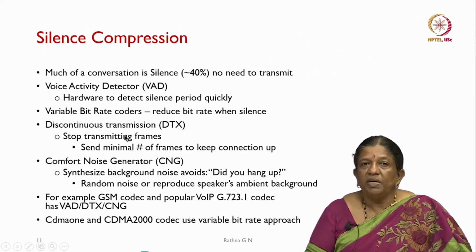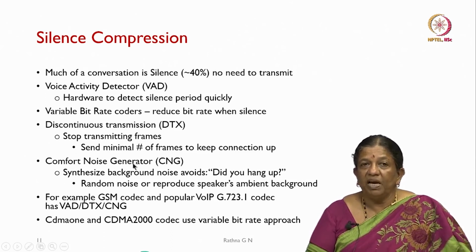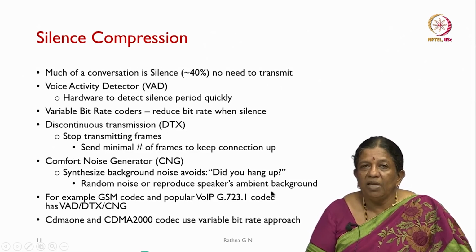Stop transmitting frames, and second, send a minimal number of frames to keep the connection up. The other one is the comfort noise generator, CNG, which is synthesized background noise that avoids the impression of a hang-up. It uses random noise or reproduces the speaker's ambient background.